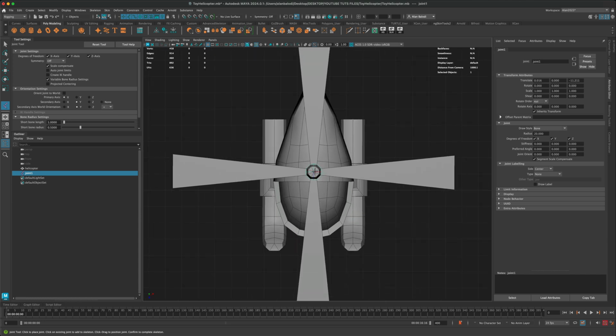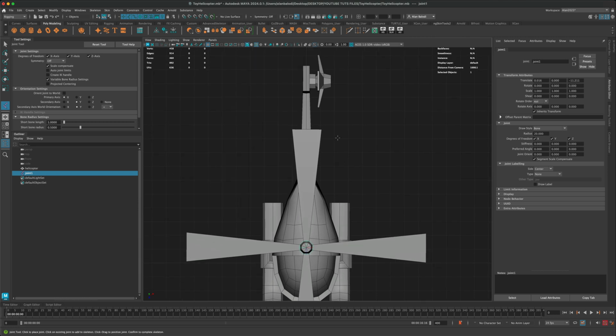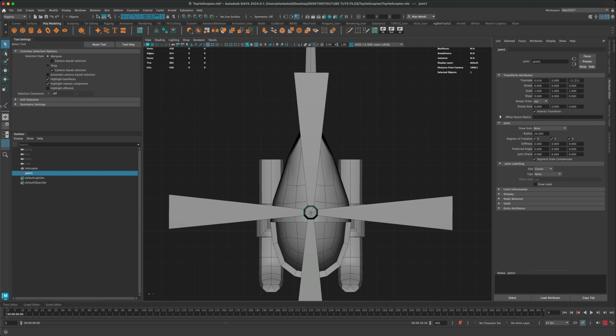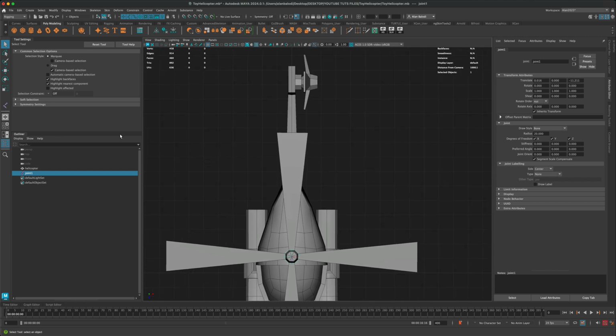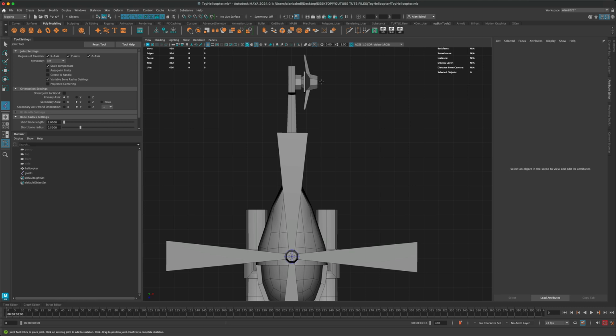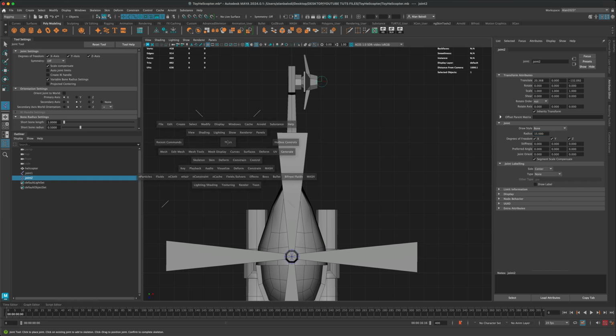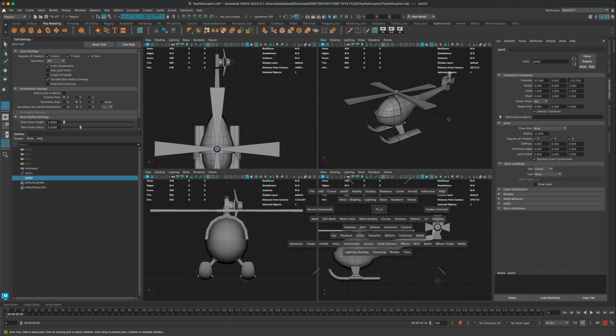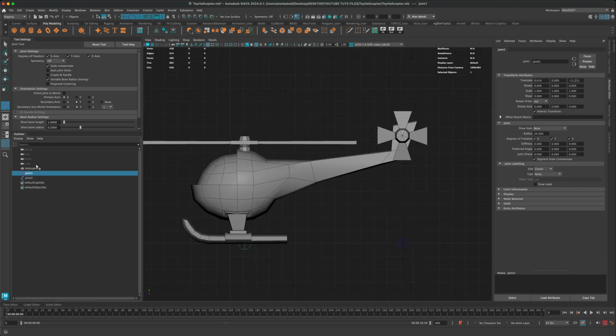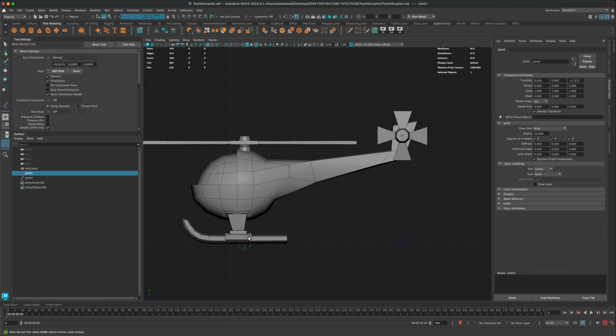All right, so this is gonna be the controller for the top blade. And let's go ahead and add one for the side as well. For that, I'm gonna press Enter to make sure that I exit the joint creation tool. Then I'm gonna select it one more time and put a joint right here. And let's make this larger as well, so this one will be 15, right? I'm going to press spacebar, jump into my side view, and I'm going to take my joint and, using the W key, I need to make sure that I am moving in the axis orientation of world. I'm going to place it right in the middle of the blade.